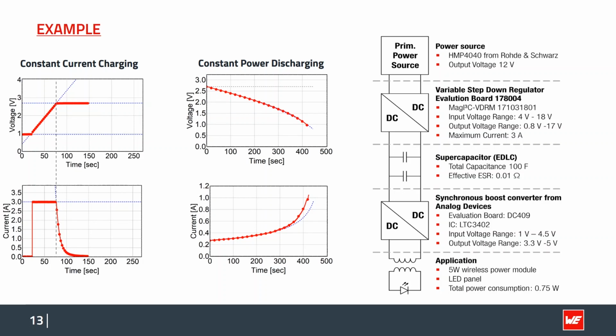This is when the difference between the charging state and the charging voltage is quite small. At this point, the current is physically restricted by the ESR. But as you can see at the voltage curve here, we really talk about small voltage differences. The supercap is practically fully charged at this point.